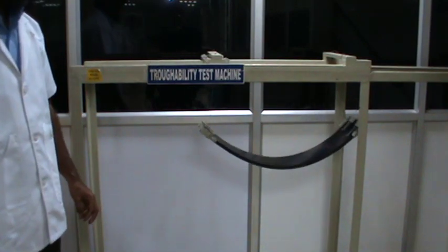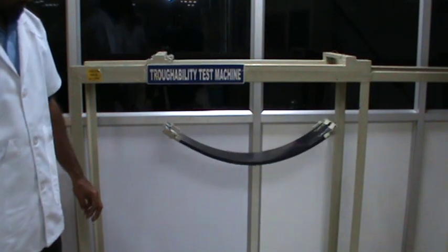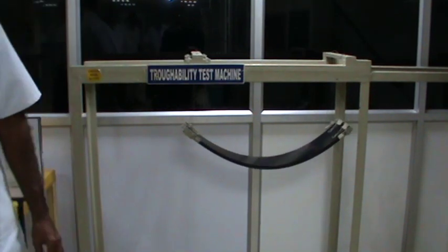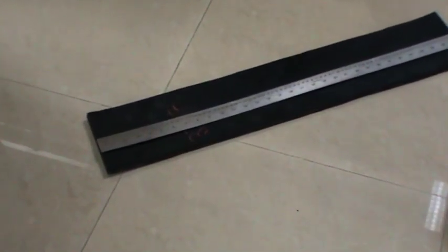If the belt is too stiff, material can spill over and the belt will wear unevenly. If the belt is not sufficiently stiff, it could fall between the idler rollers and result in pinching and delamination.